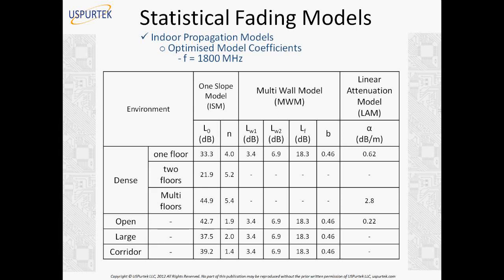If you are not happy with the way it's turning out, you may need to do your own measurements, have a field strength meter, and measure the field values in different locations in the indoor area, to determine what my path loss will be, what the power of my transmitter should be, and how sensitive my receiver will be. Or you can use these values from this table.